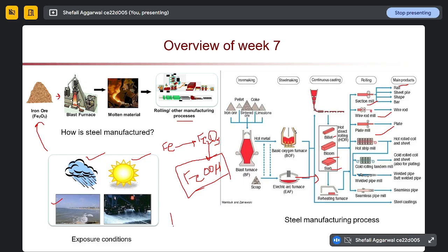happen? The iron ions will react with chlorides and form ferric chloride. This will create a pit in a normal rebar. That is one cause of corrosion. Another cause of corrosion, in our cases, is carbonation. Sorry, this is not carbonation, this is actually salination only.